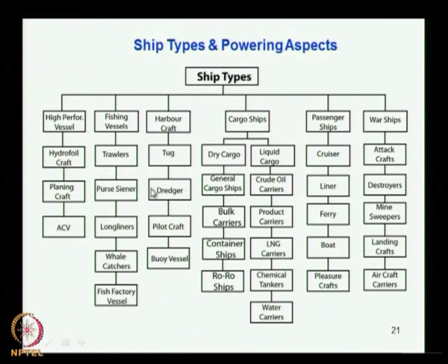Dredges: most of the harbors and waterways need dredging operation, and dredges do that. There are different types of dredges. The free running power requirement is normally less because dredges usually do not go for a longer free run. The main operation is dredging, and the power requirement will be decided based on the dredge machinery power requirement and also the hefty pumps on board the dredges, which pump out the sludge dredged from the waterway bed.